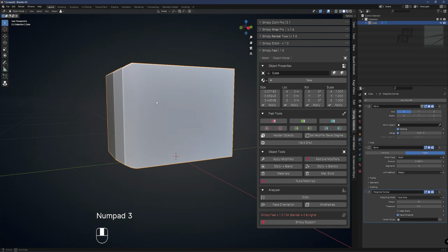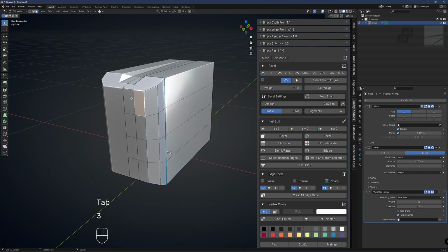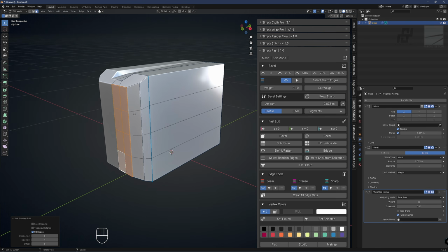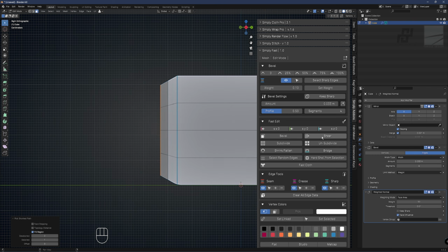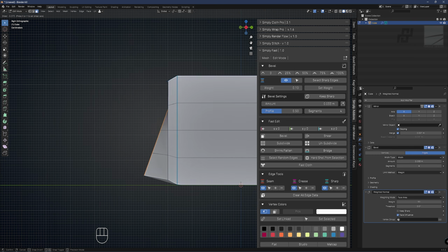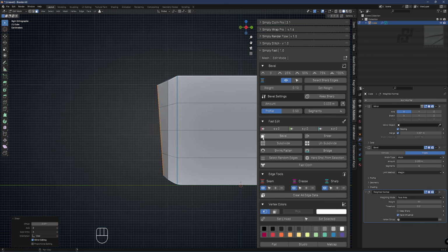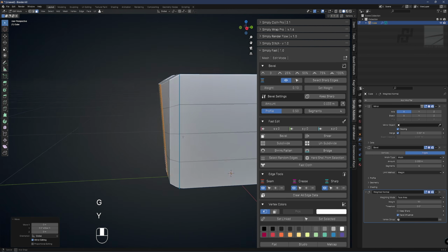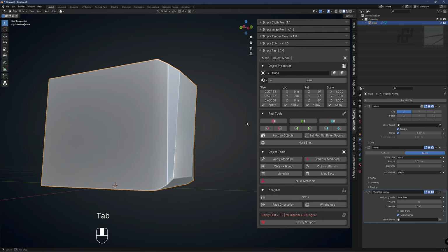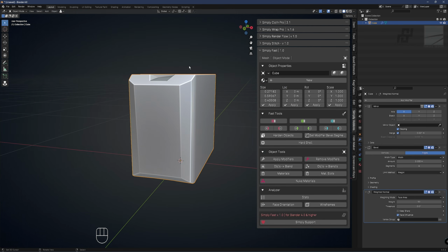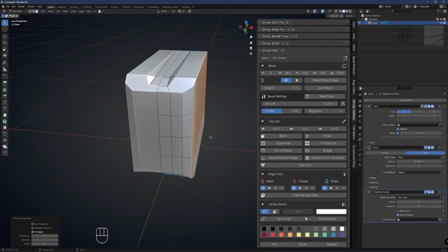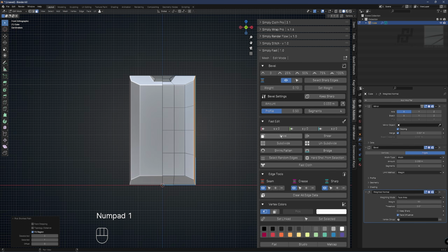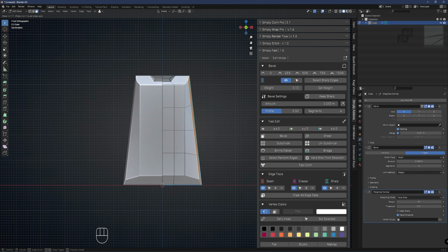So if I want a special cool design, I could select this, go in the side view and hit the shear button. So I can play with the shear directly. So we have a cool designed computer power PC tower. So we have something like that. This is cool. If I want to shear in this way, just select the needed stuff. This will be enough. Go in the front view and hit shear.